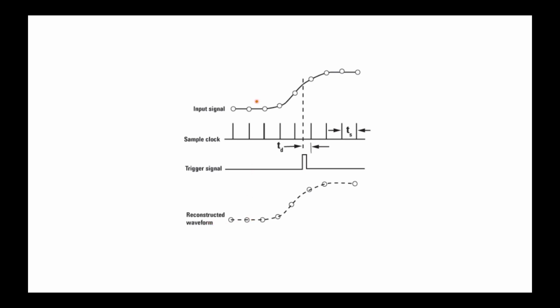And in order to do that, you have to make sure that you sample the signal based on the Nyquist criteria fast enough to avoid aliasing. And not only that, if you want to have sufficient signal integrity, you need to sample it much higher than the Nyquist criteria. And traditionally and typically up to a factor of 10, even a factor of 20, in order to be able to get a good signal. So let's say you have a 100 megahertz oscilloscope, you typically find a 1 gigasample per second or a 5 gigasample per second A to D converter that will digitize that 100 megahertz signal for you.